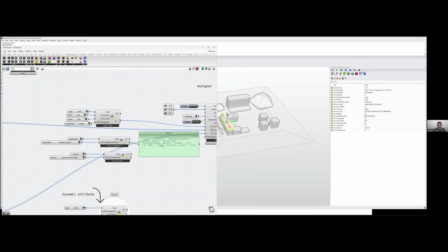But there is this kind of heuristic approach, a more informed decision, where you can assign those numbers to actual trees or porous objects like fences and so on. So it is easy to just choose what you want, and then turn it into something that behaves the way you expect a street tree to behave, for example, or a street tree during winter.